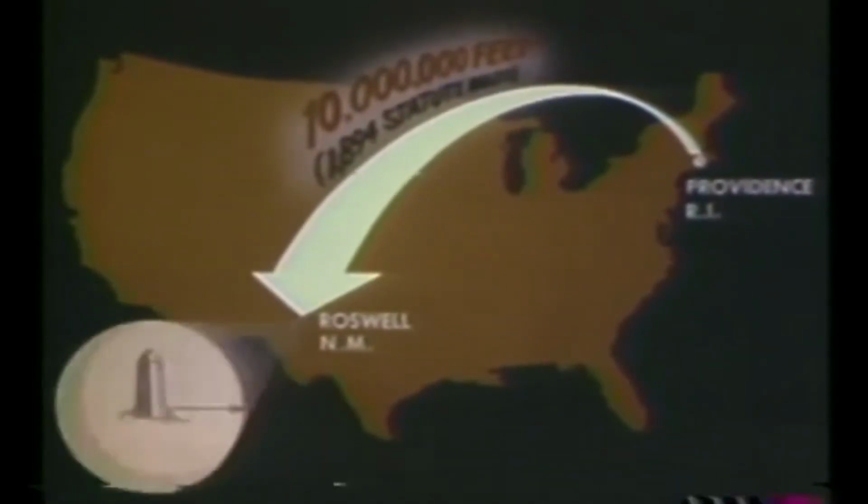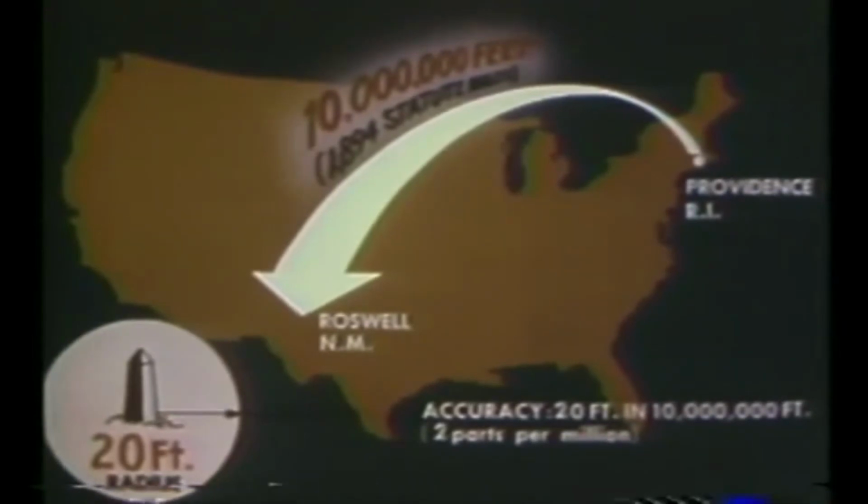The resulting accuracy in distance determination by the satellite triangulation method is at least 2 parts per million, and eventual accuracies may exceed this figure. Because the average distance of the ECHO satellite is about 830 miles from the surface of the Earth, the sides of the surface-based triangles used may be approximately 800 to 1,400 miles in length, and may easily place the respective observers in different countries of the world.